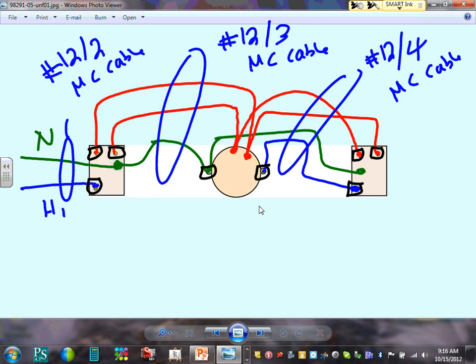You don't wire nut for the two red spots in the wire? This is a wire nut and this is a wire nut, but these are terminals though. A terminal is a lug where you land the conductor right underneath it. A wire nut, you're just tying a wire. Yeah, there are two conductors with a wire nut. Twist them. Make sense? Okay.